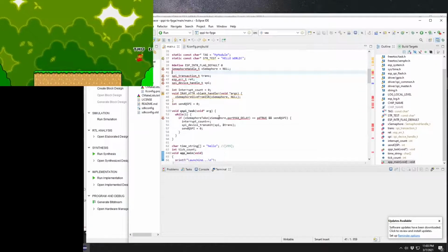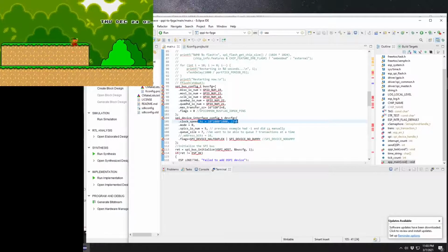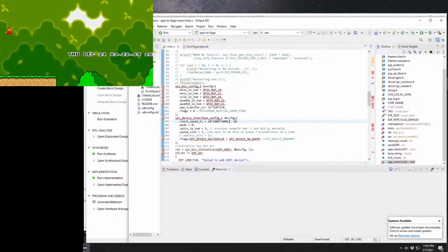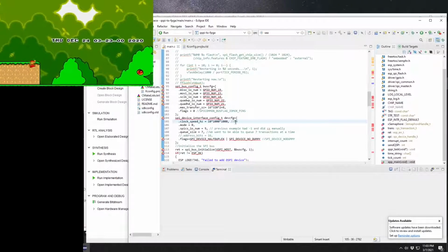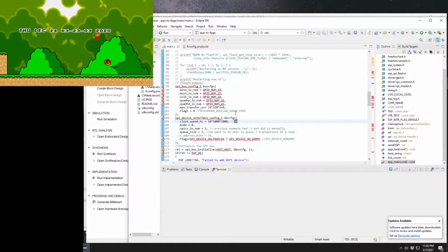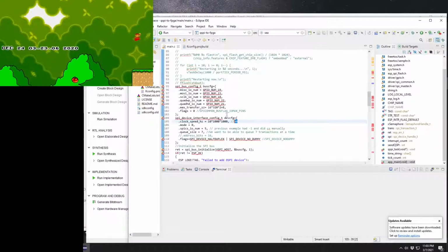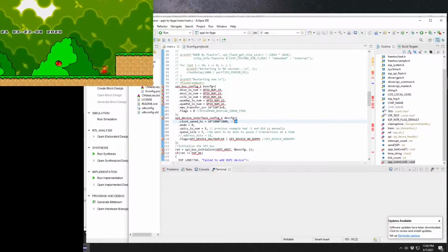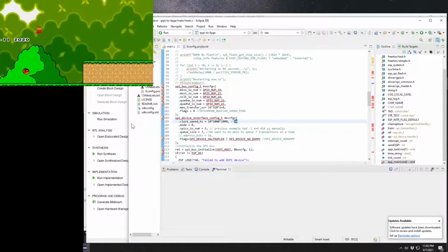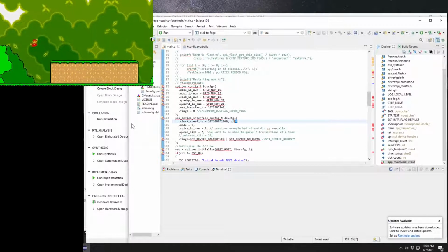The version that's in here right now is set up to send data at 10 megahertz, right here. It is capable of going at up to 80, and I'm still debugging a few other things. I didn't want to add the complication. I have found that it runs successfully at 80 megahertz, which is a lot of bandwidth. Basically, if you do the math, during the blanking period of the video being displayed, we can send about 23, or I think 26 kilobytes of data from the ESP32 over to the FPGA.